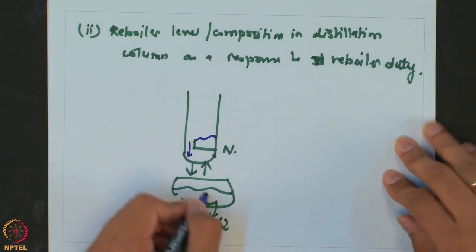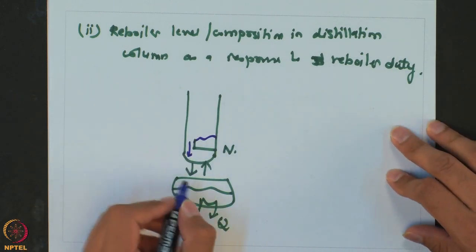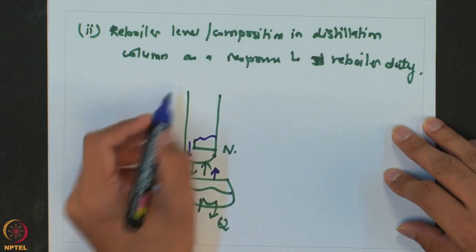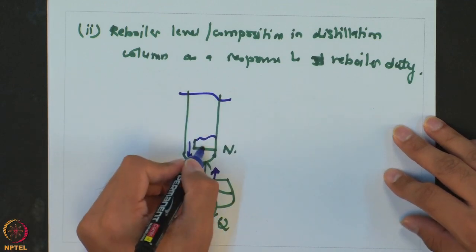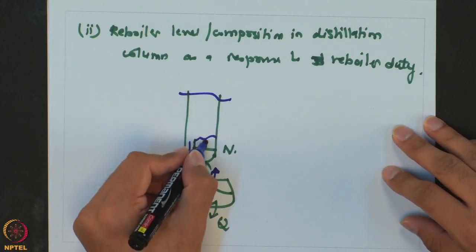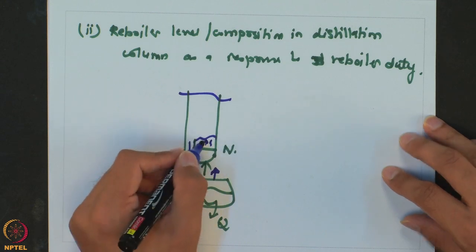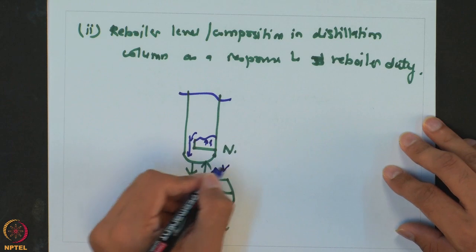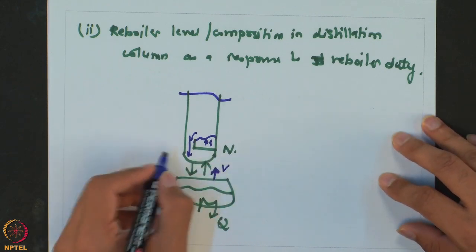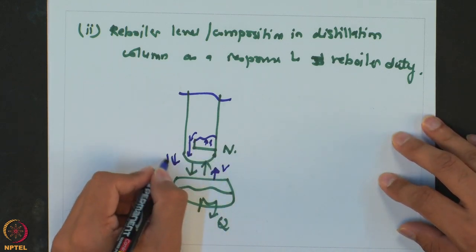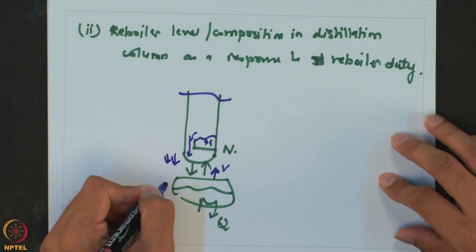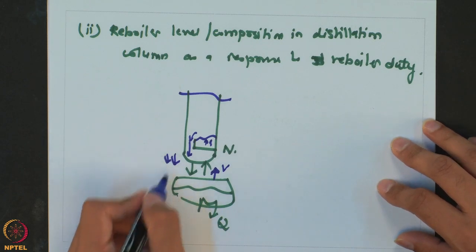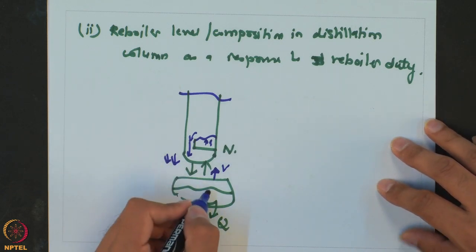when you increase the reboiler duty, the amount of vapor which goes up into the column increases, and as this vapor increases, it puts a force on this liquid which is on nth tray, and it pushes more liquid down. So, the amount of vapor increase in this case is countered by more liquid which falls down, and even though we are boiling more liquid inside this reboiler, the net hold up of the reboiler momentarily increases.